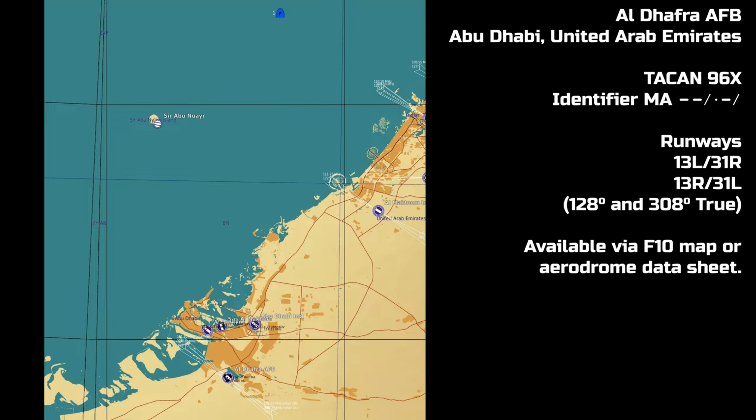In this first example, we wish to land at Al Dhafra Air Base near Abu Dhabi and have been asked to land with a straight-in approach as we would when flying an ILS landing, rather than the usual pattern approach. We will use Al Dhafra's TACAN beacon to locate the base, but want to fly towards a final approach point some distance from and in line with the runway's radial, so we can get lined up with it. For this, we will use an offset.